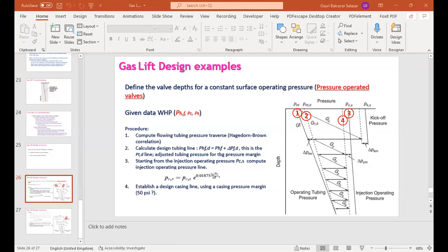So we have right here the gas lift ratio versus the rate, and again with this information we have to use the Hagedorn and Brown correlation in order to get the rate and the tubing pressure. With those new conditions, we have a plot where the rate is about 620, and the tubing pressure is 702.